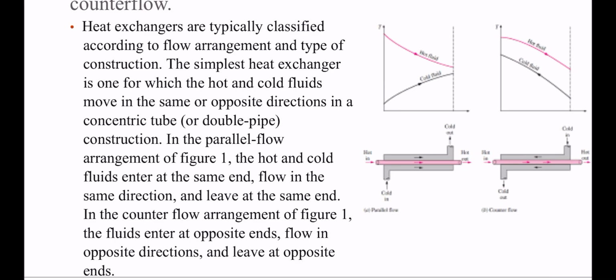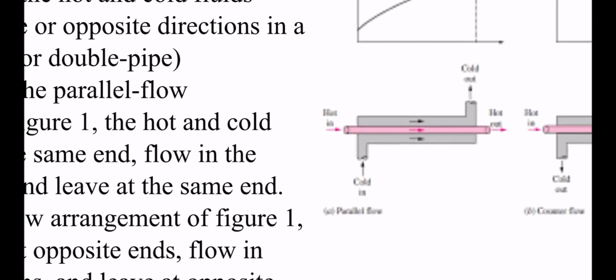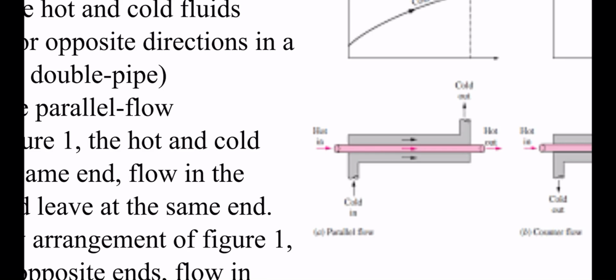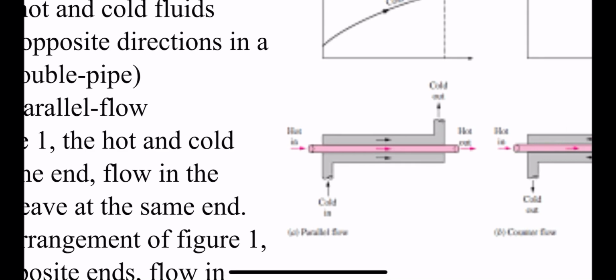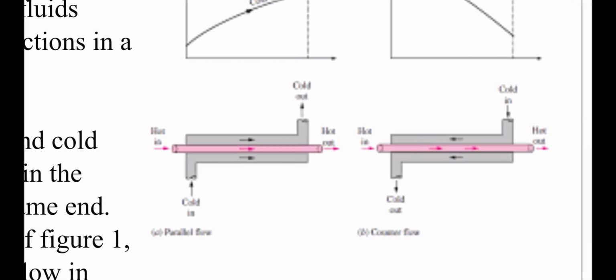Well, it's self-explanatory, but as you can see in figure 1, the inputs of the cold and hot fluid are at the same end, and the outputs of the cold and hot fluid are at the same opposite end. This is totally different in the counterflow, which has the hot input next to the cold output, and vice versa.